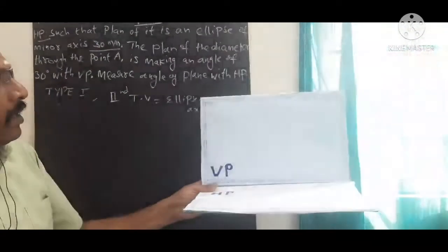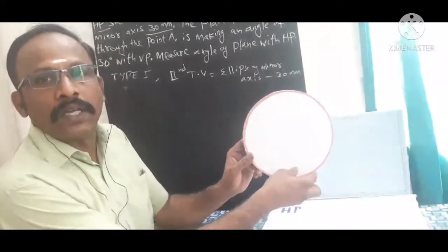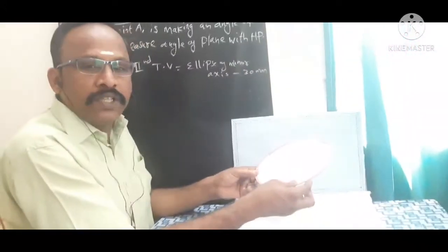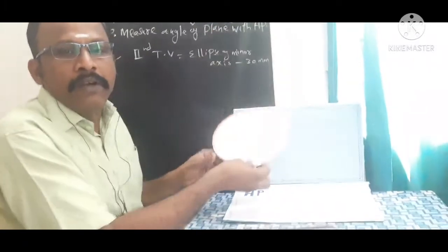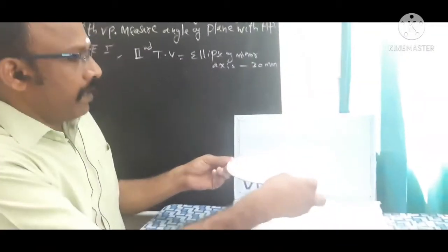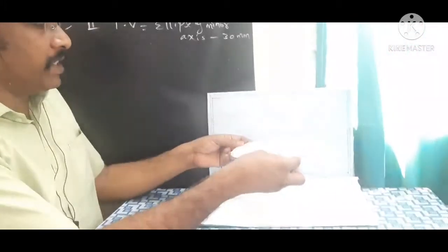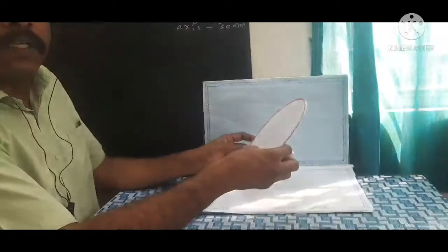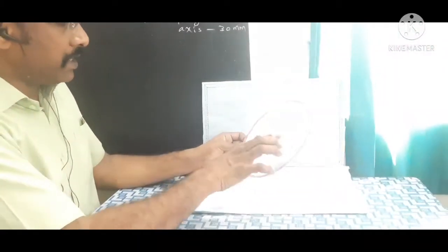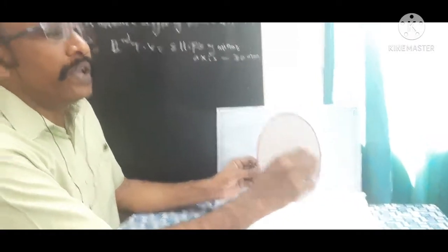So you can see the plane; we would like to keep the plane in the first quadrant system. So this is my circular lamina, right? So this is the circular lamina. Now we need to see the projections of this circular lamina by keeping, right? Here the surface is inclined to HP. So for which we need to keep like this. This is the second stage position, and that surface is inclined to VP. So for which this is a two inclination problem.